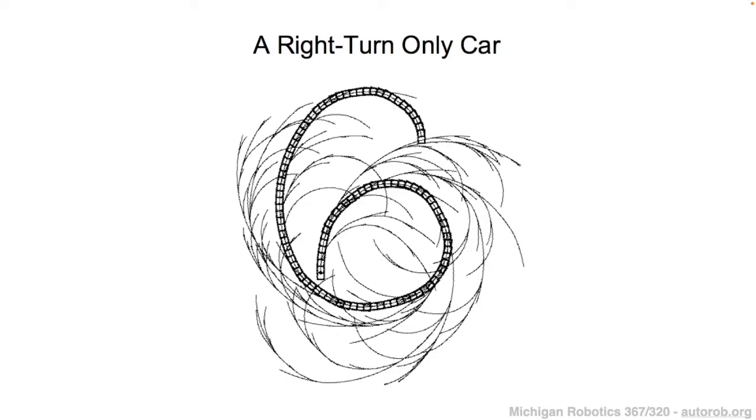And so this is desirable in the case of route planning for cars where you do have these types of constraints that you want to incorporate within your planner. The way that you would incorporate them in RRT Connect is during the tree expansion phase, where you decide whether or not a sampled node should be added.